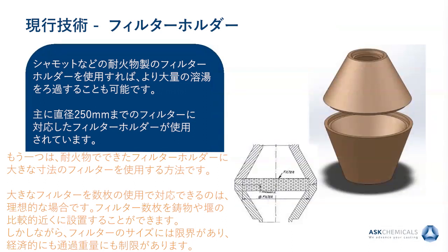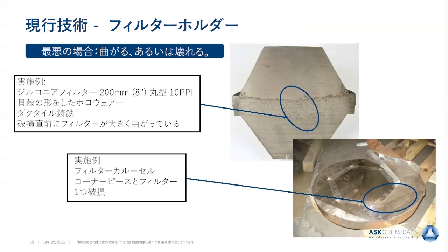However, it is possible to produce ceramic foam filters up to a maximum size of, let me say, around 300 millimeter for the iron and steel casting area. But there's also a point you have to bear in mind. It should really be noted that the thickness of the filter must be increased in parallel to the filter size. That means a filter thickness where the required priming of the filter increases so much that not enough heat can be provided by the liquid metal when it contacts the filter. This would in the end lead to an abrupt freezing of the filter and the filter is then blocked.